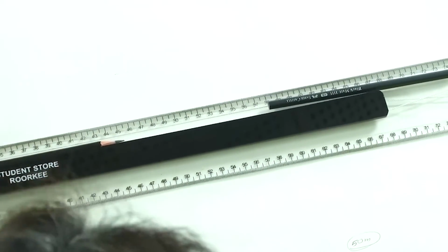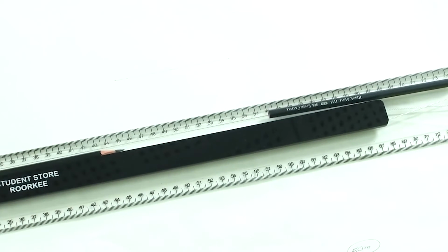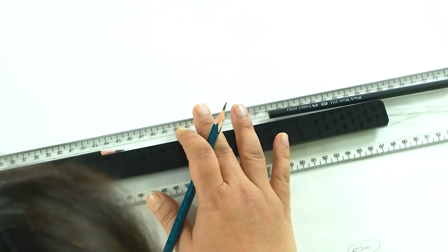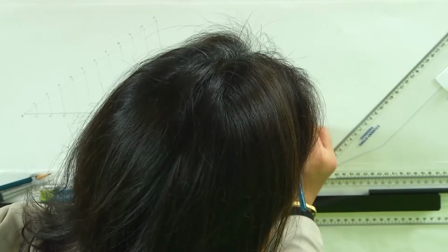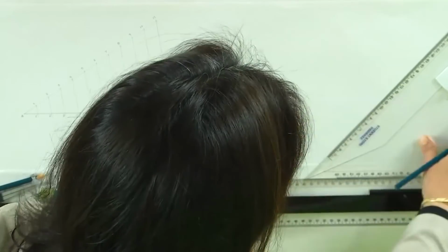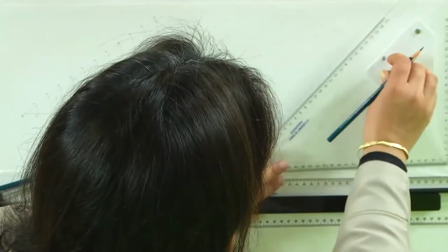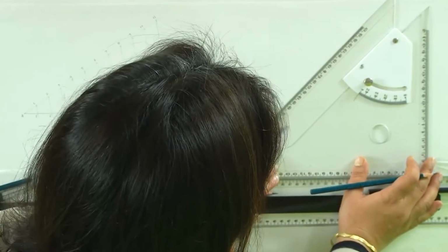Now, this one we will divide into 10 equal parts. I have already divided this line into 10 equal parts, but the very first division we will have to divide into 10 equal parts. To make those 10 divisions, I again draw a line at an acute angle, and I am again taking here a 10 centimeter line.